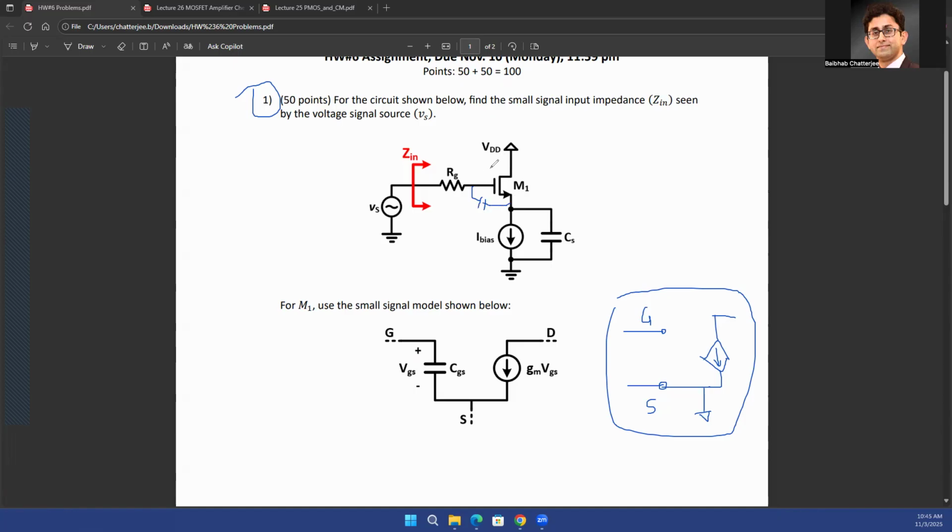There would also be a parasitic capacitance between the gate and drain terminal, and so on. In this case, we are only considering the parasitic capacitance between the gate and source terminal. But what does that mean? That means that if you are looking into the gate at DC frequencies, you'll still see an infinite impedance, right? Because at DC, this capacitor is open.